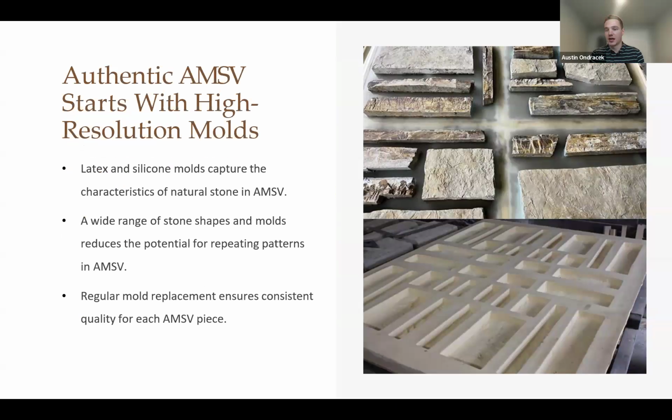This is very similar in how they pour it: they put the silicone molds in, they cure, and depending on how many molds, you can have really an endless array of sizes and shapes and textures to make sure there's not repeating patterns. There's not one similar face texture that looks exactly like the one next to it. All of that is continuously naturally reoccurring in an adhered manufactured stone.